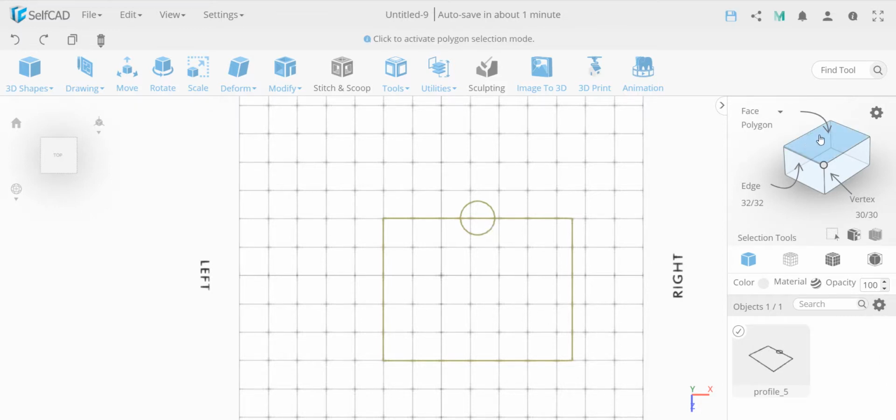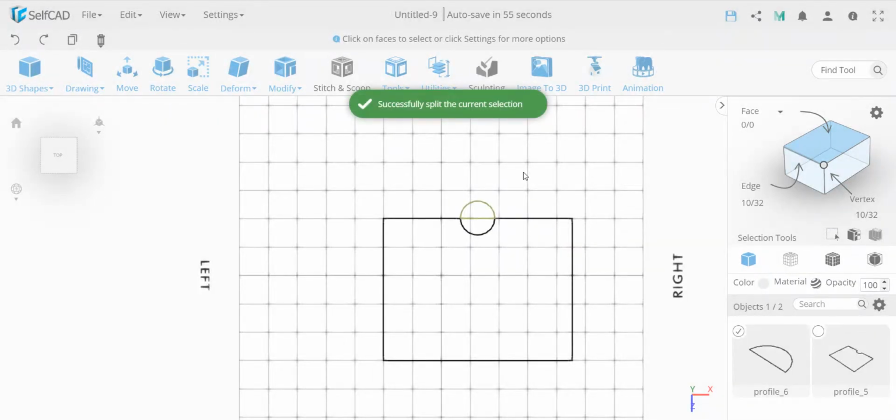So I'm going to take this and select these. I've shown before examples where I simply delete this, and this becomes kind of like a trim tool, and actually much more flexible. You can look at my video about trim that explains that. If I now press Control plus S, which is the hotkey for split, it splits it into a separate object. Now my idea is to make this, let's first fill it and then we'll see. Or first flip normals.